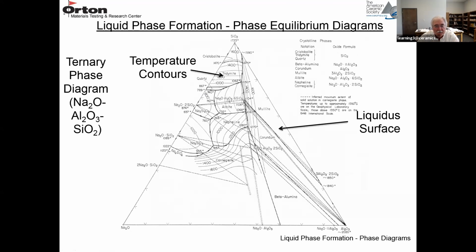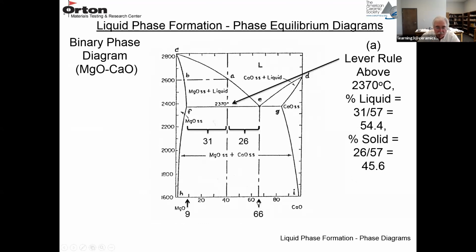Refractories, and especially in contact with slags, have multiple compounds present, so the chemistry is quite complex. It's not just going to be two phases like this. Even in a dolomite refractory, there's a number of other impurities. It's not pure MgO and CaO, which is what's shown in this diagram.